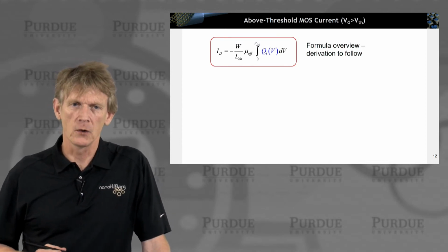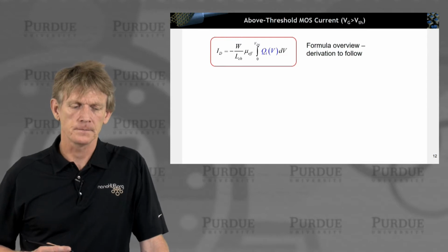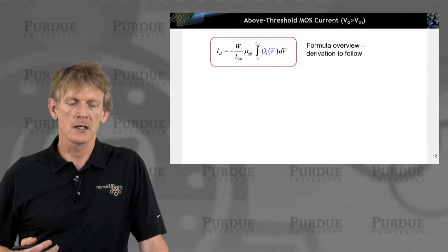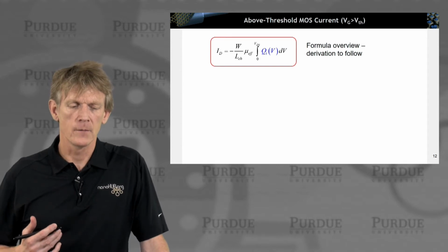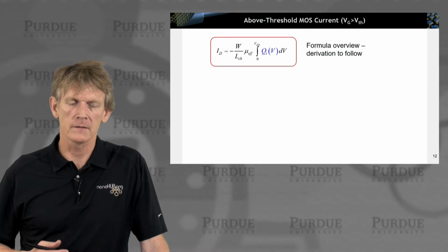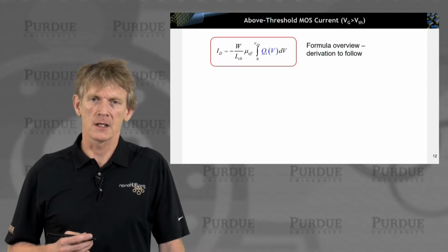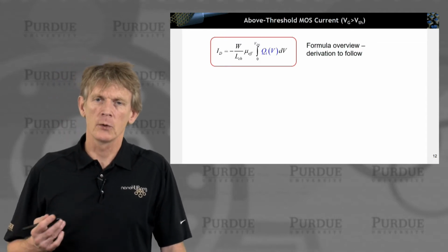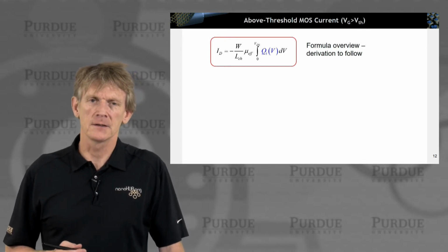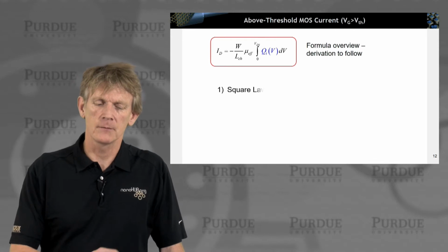We have charges flowing under the gate. We can relate the drain current to the charge flowing with a mobility across a certain width of the channel along the channel. Okay? We will overview the few formulas we'll derive in this section. So I'm just sketching them down here.